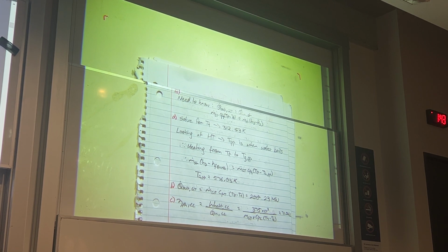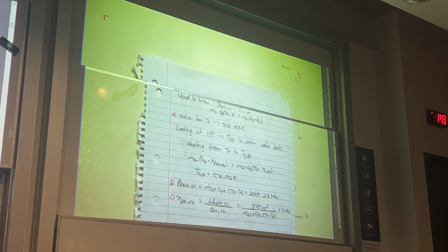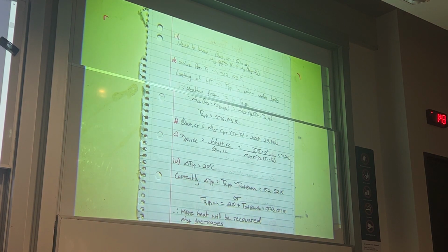So anyway, under the assumption that you know our current pinch point temp, we can go ahead and solve this. So they say that the minimum is 20 degrees Celsius. And pretty much what we're going to do is a comparison: if we were to use 20 degrees Celsius or our current pinch point temp, what modifications to the cycle would be required, specifically in how much work we can extract from the Rankine cycle.